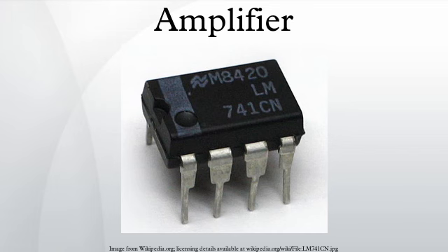The Doherty amplifier consists of a Class B primary or carrier stage in parallel with a Class C auxiliary or peak stage. The input signal splits to drive the two amplifiers, and a combining network sums the two output signals. Phase-shifting networks are used in inputs and outputs. During periods of low signal level, the Class B amplifier efficiently operates on the signal and the Class C amplifier is cut off and consumes little power. During periods of high signal level, the Class B amplifier delivers its maximum power and the Class C amplifier delivers up to its maximum power.